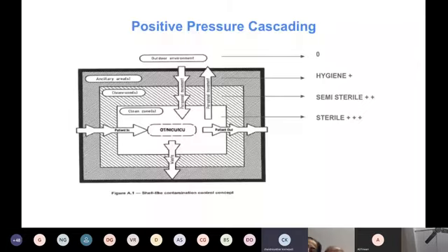This kind of zoning helps us to sweep. We make the air scavenge the total area completely, from the highest pressure to the lowest pressure. The highest pressure will be in the OT, NICU, ICU, and all other critical cubicles and areas.